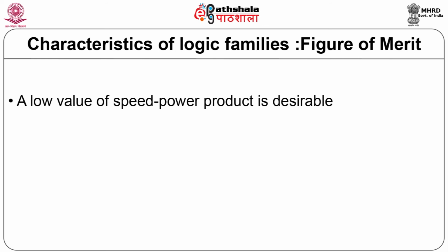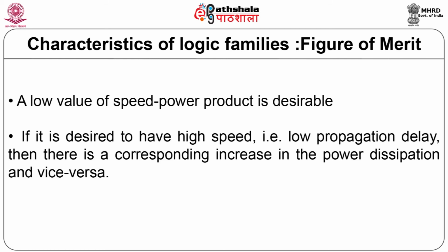A low value of speed power product is always desirable. If it is desired to have high speed, that is low propagation delay, then there is a corresponding increase in the power dissipation and vice versa.